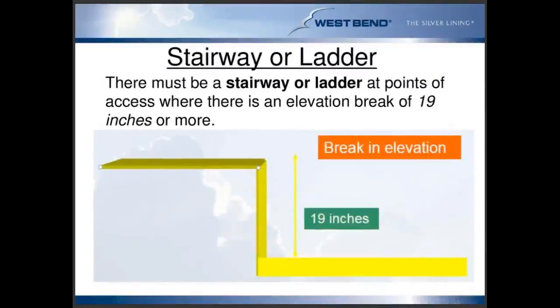So when looking at the OSHA requirements for when we need to have a stairway, ladder or ramp, it's not too high of an elevation. They say at any break in elevation of 19 inches or more, we need to have one of those in place. And typically at a smaller elevation like 19 inches, we're not going to find a ladder.